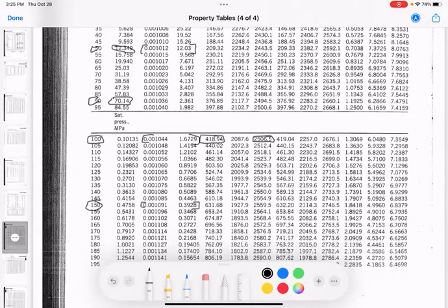Good. But we don't know how far down the line we are in terms of our quality. So instead of using the quality to find our values right now, we're going to use our known value of specific volume to find the quality. And once we know the quality, we can find the internal energy by going that much percent of the way between these two values here.